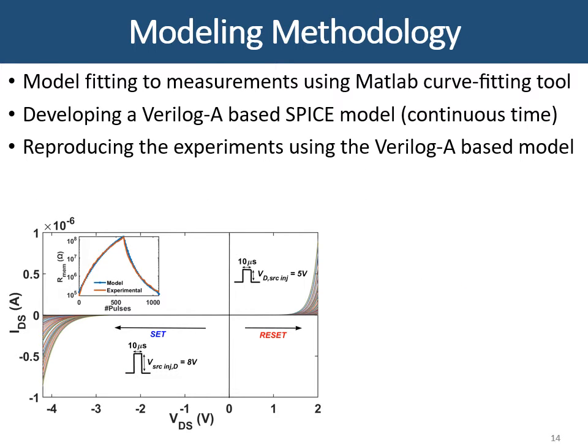Here we specify our modeling methodology. As mentioned, we fitted the experimental measurements to the analytical model equations using MATLAB curve fitting tools and simulated annealing techniques. Since the model is dynamic and has continuous time kinetics, it could be easily implemented using a Verilog-A SPICE representation.